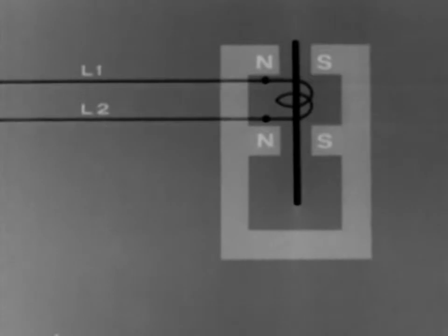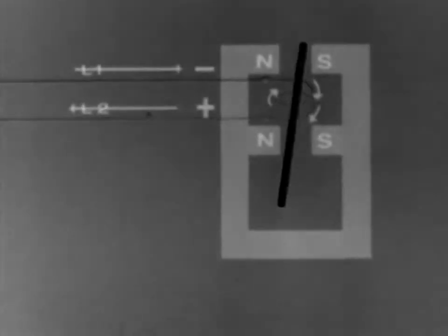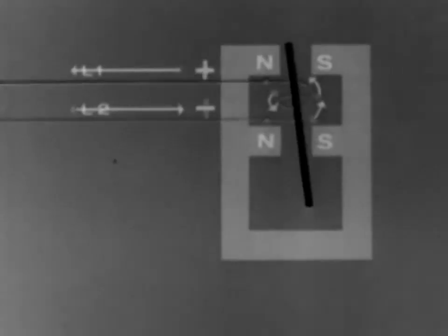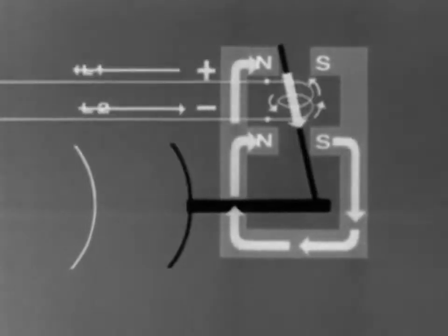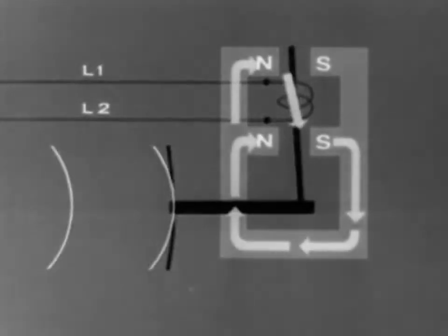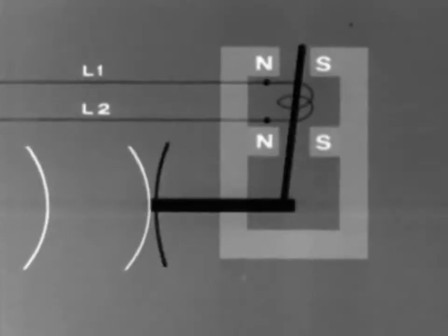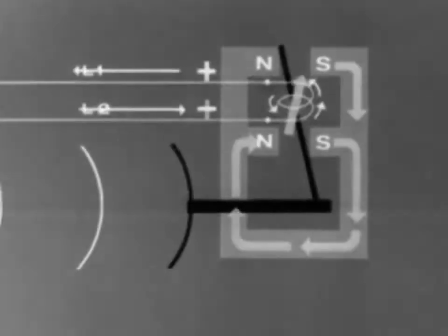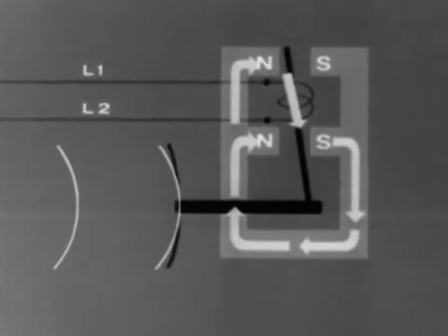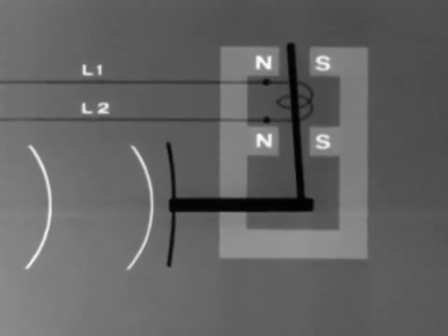The armature is surrounded by a coil. As the polarity of the armature changes, it induces an alternating potential in the wire. By attaching a connecting rod from the armature to a diaphragm, similar to that found in a telephone transmitter, a direct linkage is effected. The energy of sound waves moves the diaphragm. Because of the direct linkage, any movement of the diaphragm is transferred to the armature. This means that an alternating potential will be induced in our coil, which exactly corresponds to the wave pattern of the sound waves.